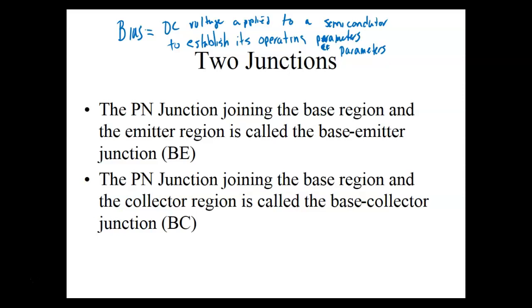So with diodes, we can only forward bias it or reverse bias it. If we forward bias it, it does what? It conducts. If we reverse bias it, it cuts off. But these are seen as DC voltages, even though we put an AC voltage on it. One alternation is going to be seen as a positive DC, which might forward bias it, but the other one's going to be seen as a negative DC at the same time.